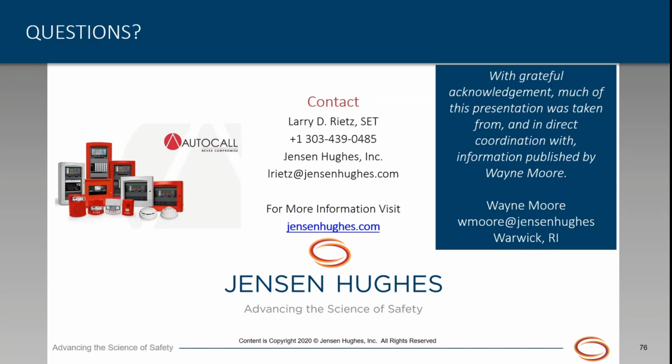Now, you can get 2-hour rated enclosures, just like you would have a 2-hour rated access panel for a shaft, as an example. So you can get that on the market, but again, you want to use the junction boxes that are listed with the survivable cable where you can, and then if you're having to do it outside, you're going to have to look at alternate ways to meet that requirement.